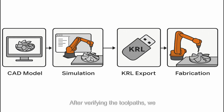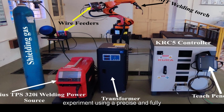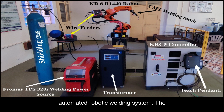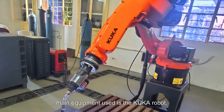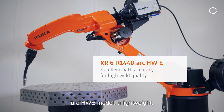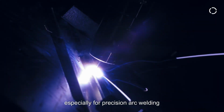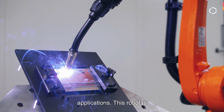After verifying the toolpaths, we exported the KRL code onto a USB and loaded it into the robot via USB. Using the KUKA Teach pendant, we ran the program to begin fabrication. To carry out the wire arc additive manufacturing process, we set up our experiment using a precise and fully automated robotic welding system. The main equipment used is the KUKA robot, specifically the KR6R1440-2 Arc HWE model, a lightweight, high-speed robotic arm designed especially for precision arc welding applications.